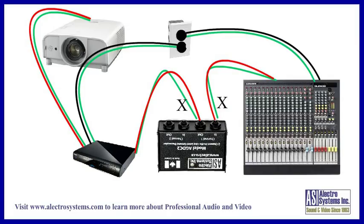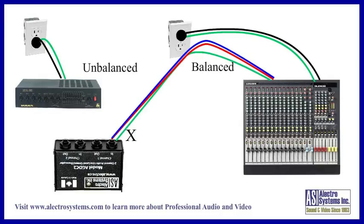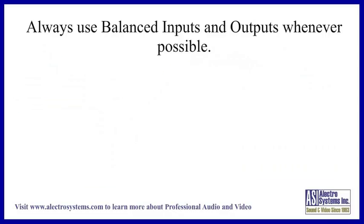Another common use for the AGDC2 is to connect the sound from your main sound system to a remote amplifier in another room, maybe used for overflow. Often the mixer output is balanced, but the input on the remote amplifier is unbalanced. Run balanced cable from the main mixer output to an AGDC2 located beside the remote amplifier. Then unbalanced from the AGDC2 to the remote amplifier input. This way you can usually interconnect the two with no trouble at all.